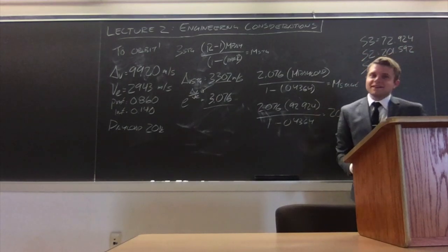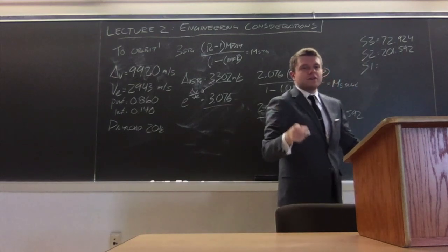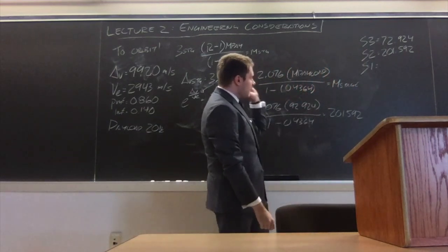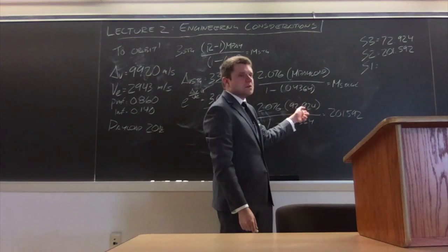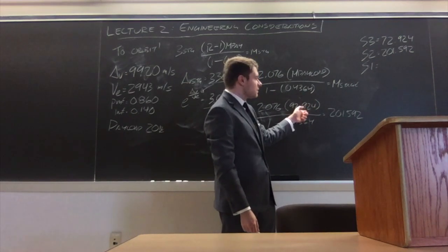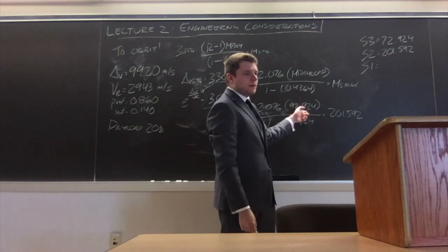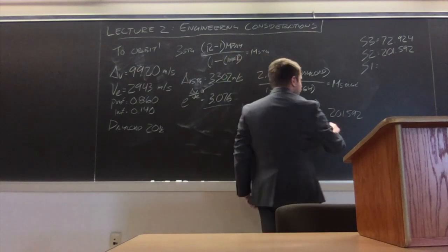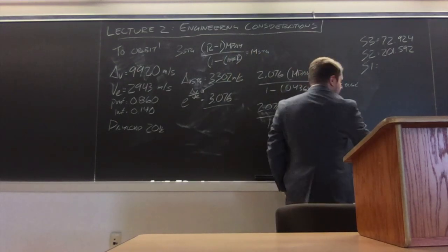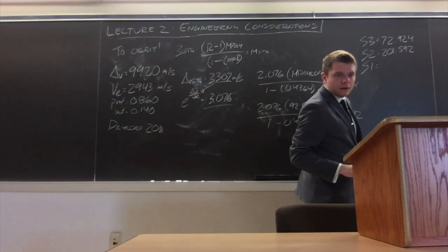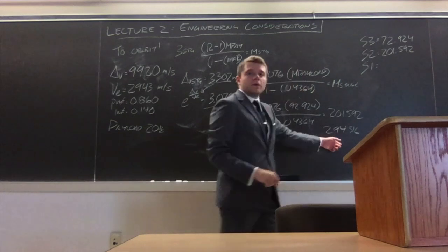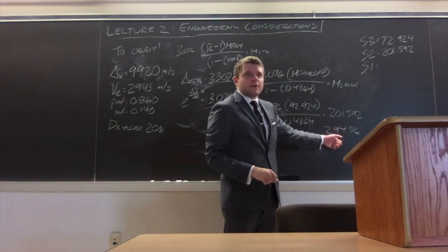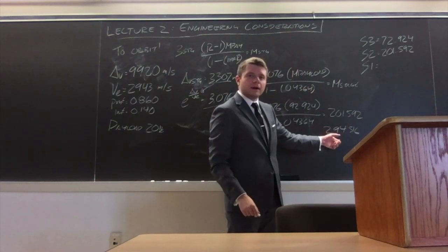But we're not done yet, because for the final stage in our 3-stage rocket, we have to take this number and add it to the payload of that stage to figure out how much mass the first stage has to push. So we do that, and we find that we get an approximate mass of 294.516. That is our new payload mass for the first stage of the rocket that fires. It's taking this much payload behind it.